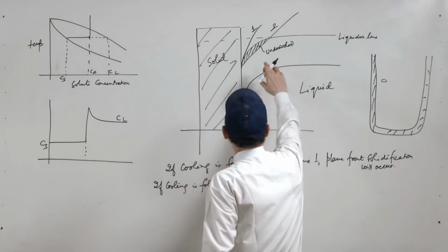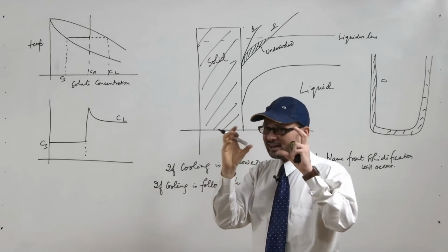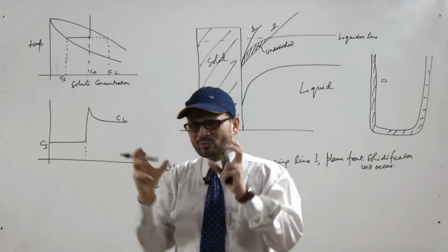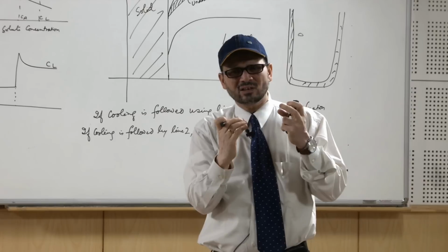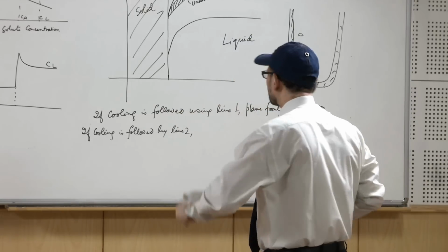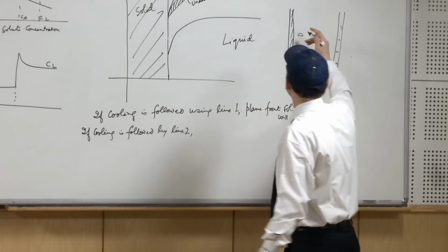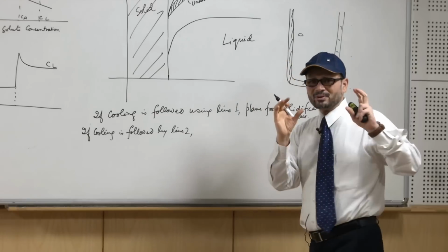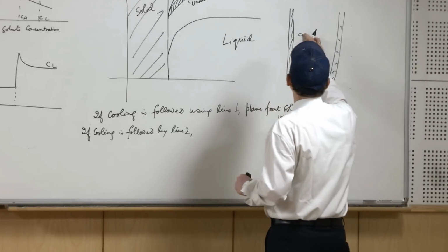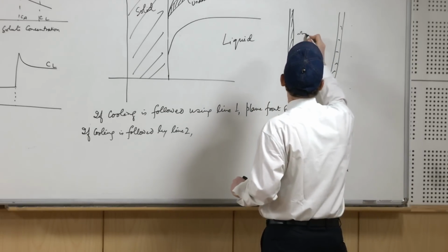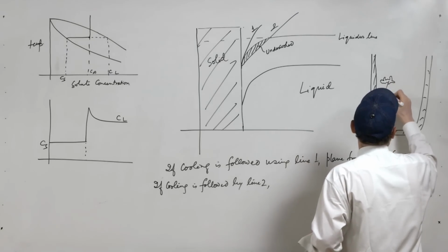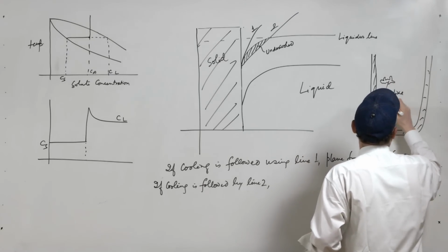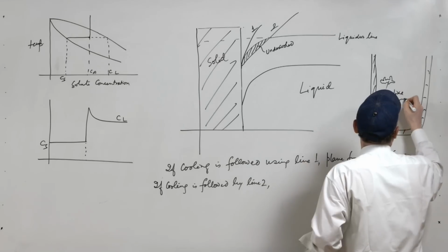Now, since it is an isolated mass in the liquid, there is no preferred direction of heat flow at that particular point. So, it will grow in all the directions having certain preferred direction, and normally it looks like a dendritic structure. So, it is a tree like structure, or dendrites.